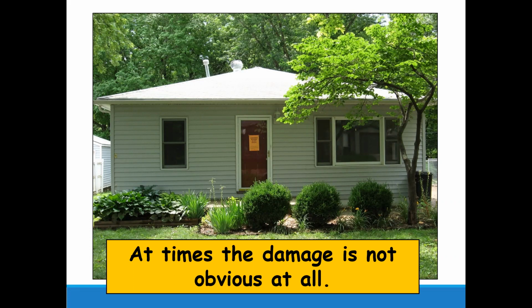And again, this house could be substantially damaged. You might not see that on your windshield inspection, and so we suggest you start by just driving around and getting an idea of the areas that are damaged and how badly. So it turns out in this house, the entire back side of the foundation is just hanging out over open ground, and so it's not stable. It's just empty underneath the foundation in the back, and so that's not something you would see from the front. You would have to do the inspection inside and go around the outside.